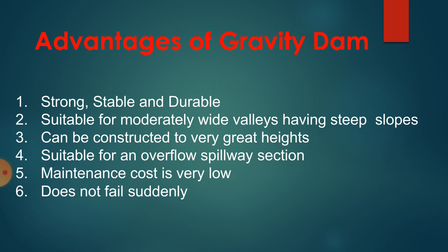Fourth, it can be well adapted for use as an overflow spillway crest. Earthen dams cannot be used as overflow dams. Fifth, the maintenance cost is very low, and the next advantage is it doesn't fail suddenly.